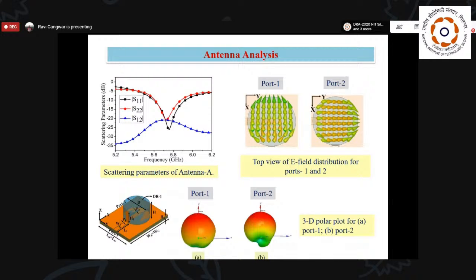So here you can see that we have more than one antenna element. Our first condition is true. Then we see whether both antennas share the same impedance bandwidth or not. That is also true. And here you can see the isolation is better than -20 dB. And here you can see that we are able to generate two orthogonal modes. Clear? So all these conditions are fulfilled here.